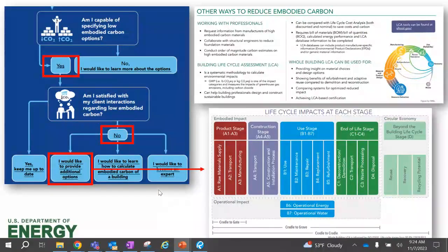There's many programs you can do life cycle assessments in. It's definitely more of a design tool. I wouldn't say that this is something that we would do often as general contractors, but being aware that the LCA exists on the project is important. Life cycle assessments, again, are part of LEED as well. You can get a point associated with just doing a life cycle assessment, and then you can get additional points by reducing your carbon impact based on that LCA.